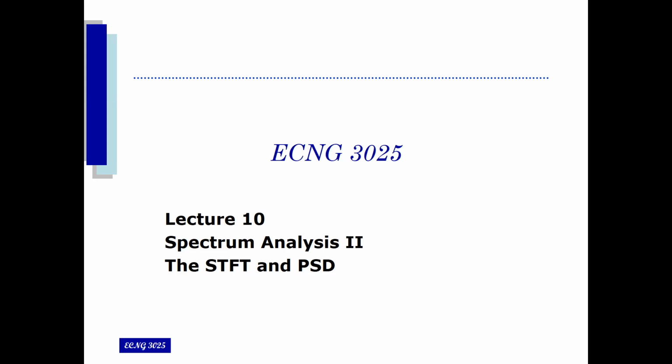And we saw that the rectangular window actually was the worst of the lot because of the sinc function behavior of its spectrum. So we ended up by looking at some other modifications that improve on the performance of the spectrum windows. And we looked at the triangular one, which had some issues in that it starts at 0 and goes up to its peak and then starts to decrease immediately. Or the more common ones are based on a cosine function.